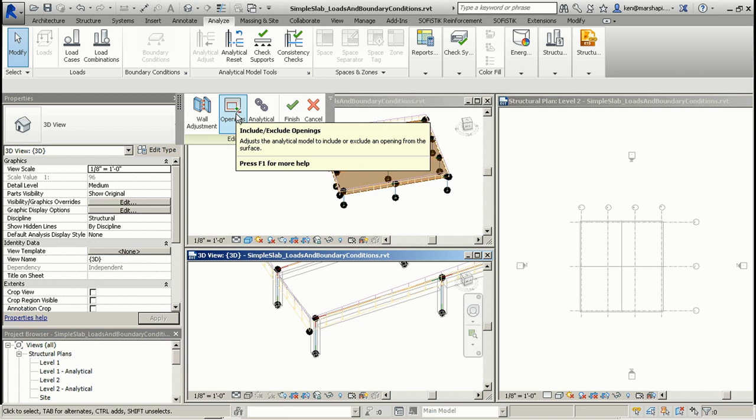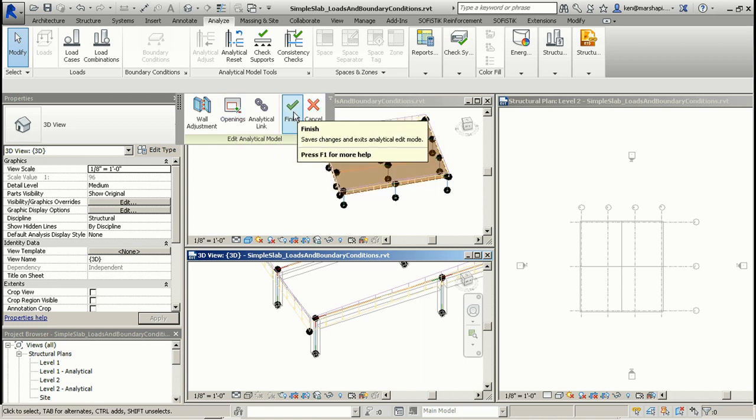Openings can be included or excluded. If you have a large opening, obviously you want to include that in your slab or wall. But if you have a small opening or a bunch of small penetrations, you may not want that complexity in your analytical model, with a thousand little elements around those tiny openings. The openings tool allows you to just ignore those small openings. They get little check boxes on there. Let me show you what that looks like.